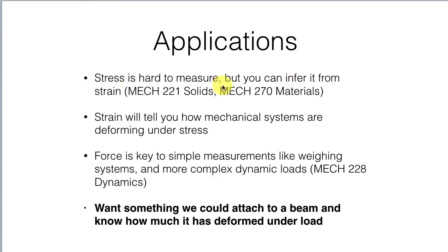Applications? Well, stress is hard to measure, but you can infer it from strain. And you'll get that in some of your other courses in solids and materials. And the strain will tell you how mechanical systems are deforming under stress. And we're particularly interested in being able to measure forces. And if we can measure a force applied by how much our beam bends, then that would be advantageous to us as a force measurement device.